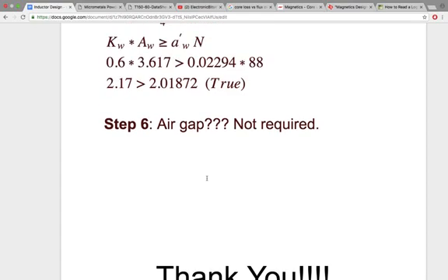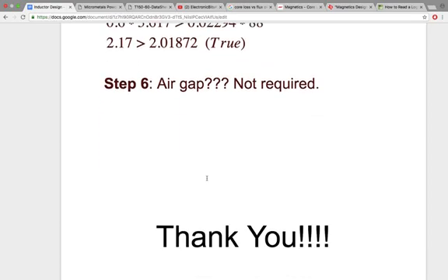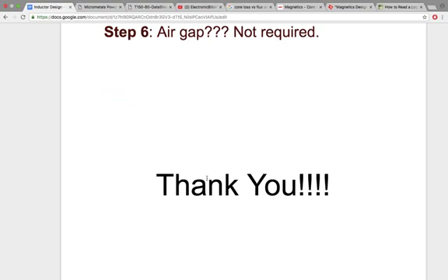And you can see that using an iron powder core, the area product has come down. So as a result, the size of the core has also come down. There are a lot of good quality cores also, which you can look up on websites like Magnetics, Micrometals, Digi-Key, and other websites. So there are a lot of places you can look up and you can design.